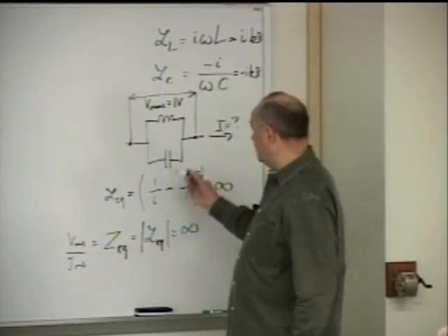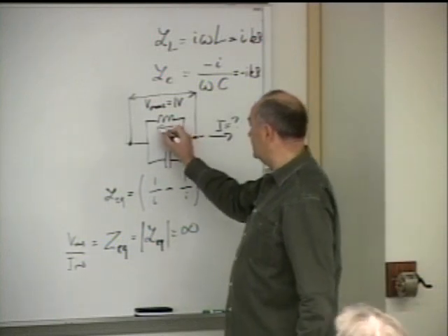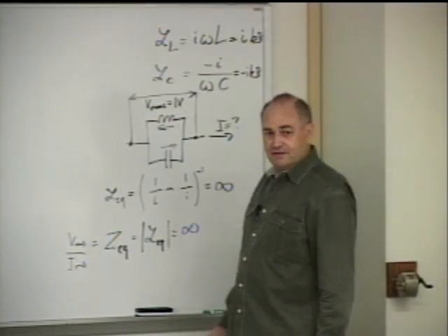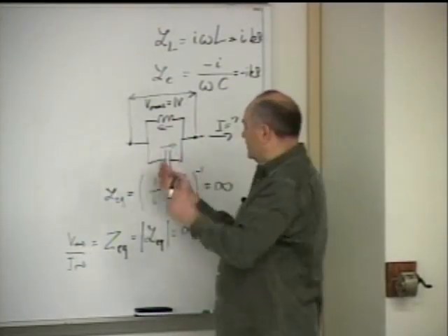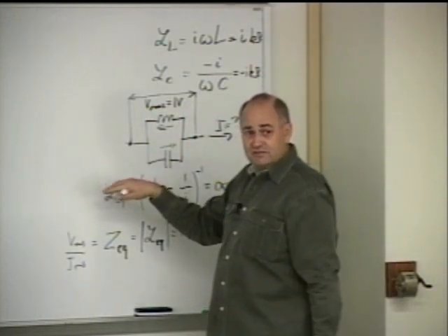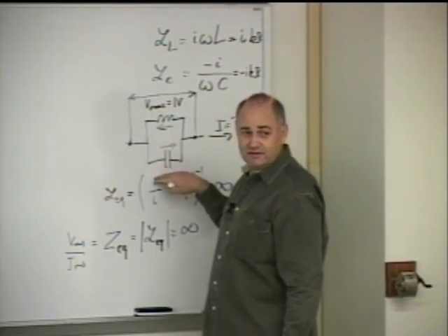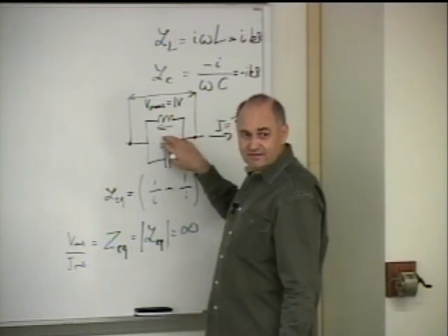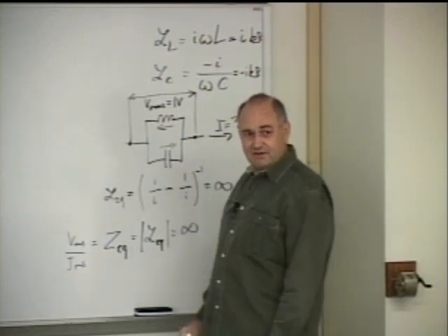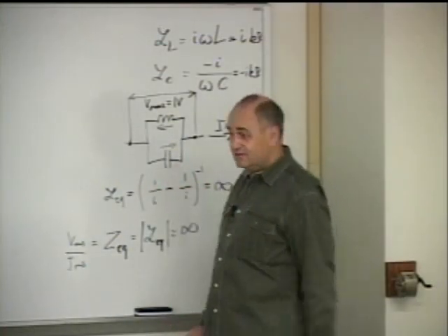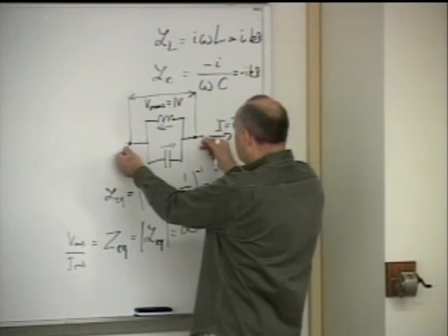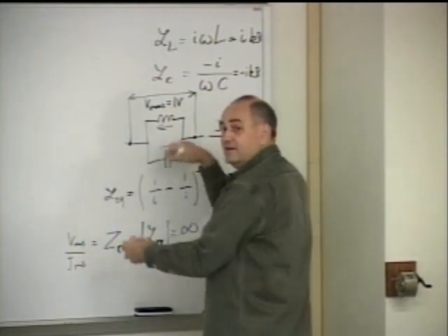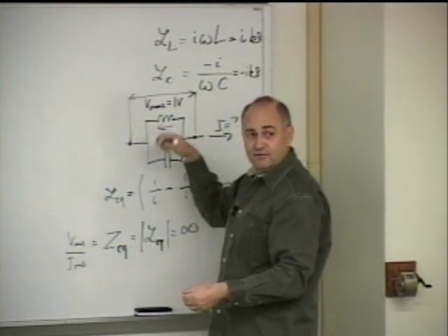What happens is that whenever current in the inductor flows to the left, current in the capacitor flows to the right. And when this one changes direction, this one changes direction. The currents in those two are always equal in this situation. So currents flow in both, but they add up to a 0 current because they always flow in the opposite direction. So we apply a source of alternating voltage over here, and we make current to go crazy in that loop, going only back and forth.